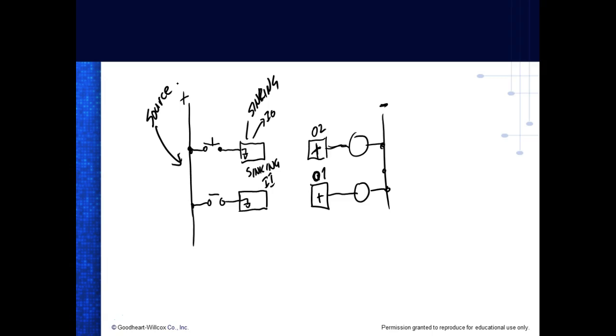Like put a barrier on the wrong side. Or connecting both your lights to the positive terminal, right? But these systems basically all input. The input devices are plus. The ports themselves are sinking for these PLCs. And this is true and this is not true for some PLCs.